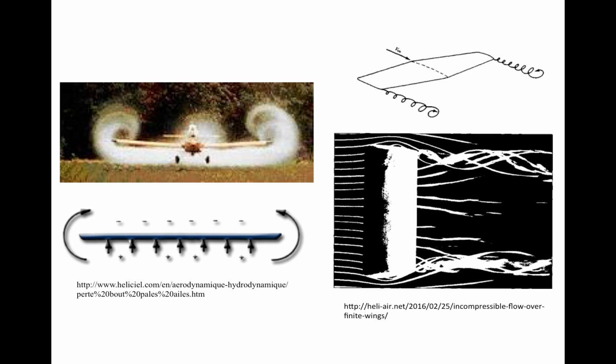This is the 10th video about the wind turbines. In the last video, we talked about the classic blade element momentum method, or BEM. In this video, we will discuss two highly important corrections to the classic BEM. One is called the Prandtl's tip loss factor, and the other is the Glauert correction for high values of the axial induction factor.